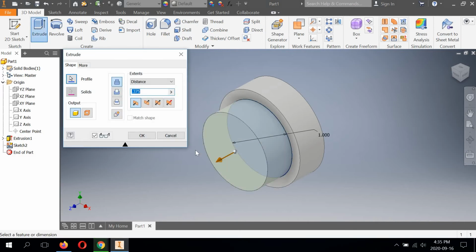And we're going to extrude it. Now, how much do we extrude this diameter? The sheet doesn't actually tell us. So what we need to do, we can look at the length. The length is given. It says the entire punch is 2.375 long.